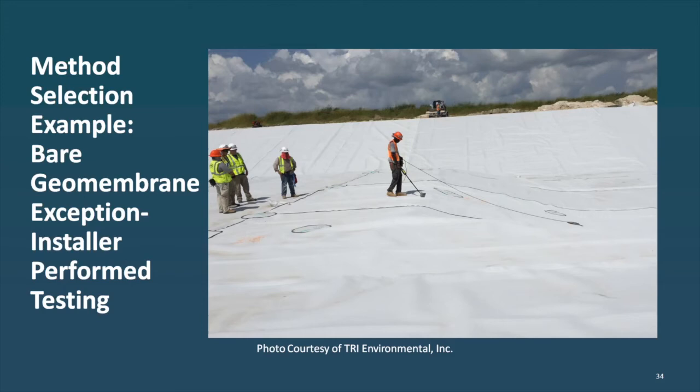So that way you don't have to mobilize a third party. It's a lot cheaper to do the testing. And the only real thing that can go wrong is if the installer doesn't do it right. But if you have a one-day audit of someone who used this test method as a third party, you can make sure that they're testing properly. And that way you get your entire installation tested while bare, so that you get the most sensitivity of all the methods, and you pay a lot less for that liner to be tested that way.